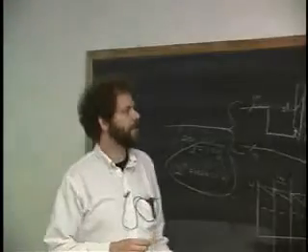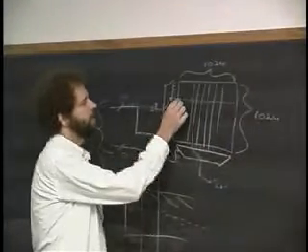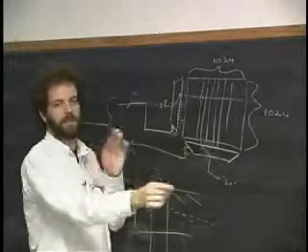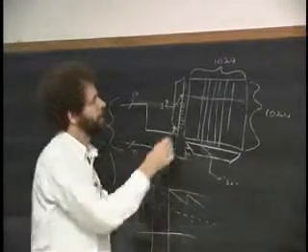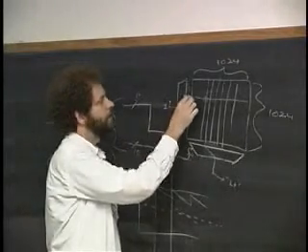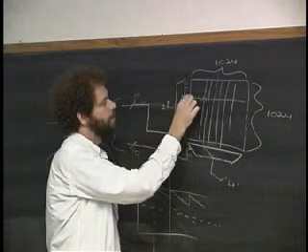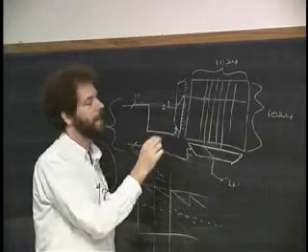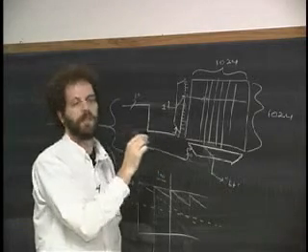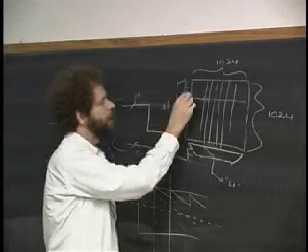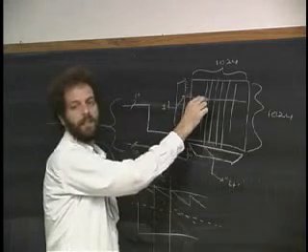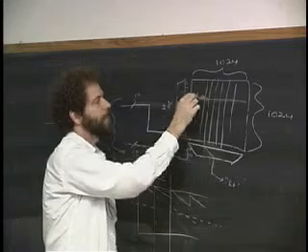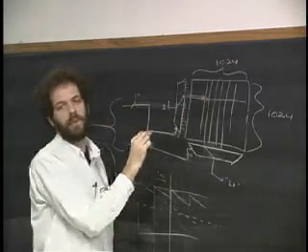I totally get what you're saying. You're worried that the wires here may be thin and long, like a river, kind of going a long distance, and it's not a very wide river. And so if we put a lot of energy in here, it may have some resistance before it gets to the junction, right? That's absolutely right. And the designers of these chips take great pains to figure out, if I put a high voltage here, what's it look like here? And it turns out that it changes how fast it takes for the high voltage to get to this place. And we're going to talk about that.